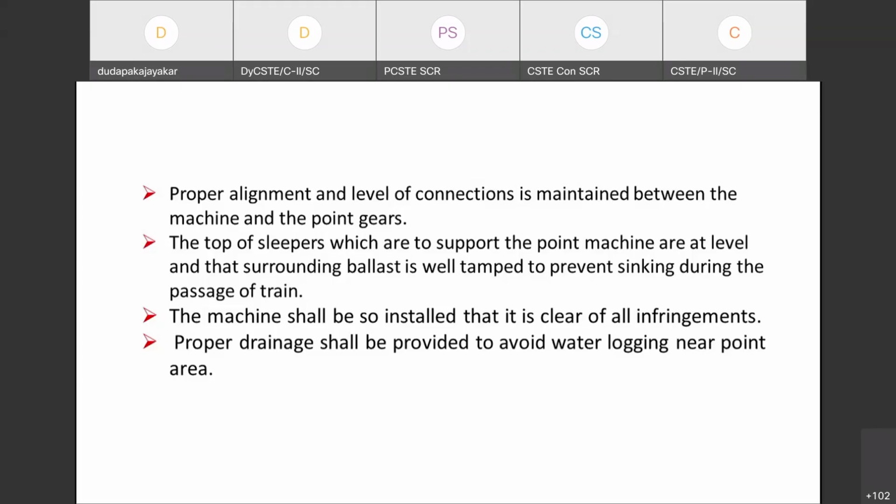Intermittent failures may be because of loose packing, sir. While a train passes over, under the wheel, the indication will get disturbed. Also, because of insufficient contact pressure, sometimes the point may get locked but the detection will not be proved. So loose packing and insufficient contact pressure should be checked during inspections or maintenance.